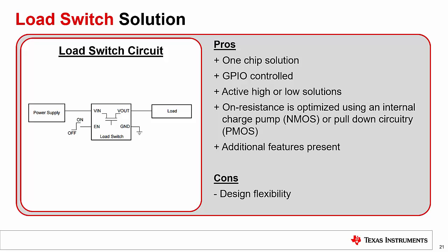The only con here is design flexibility, since a discrete solution can use any MOSFET needed for the application, and there are thousands of MOSFETs to choose from. That being said, there are many load switches available, and some can even be configured to better suit a specific application.